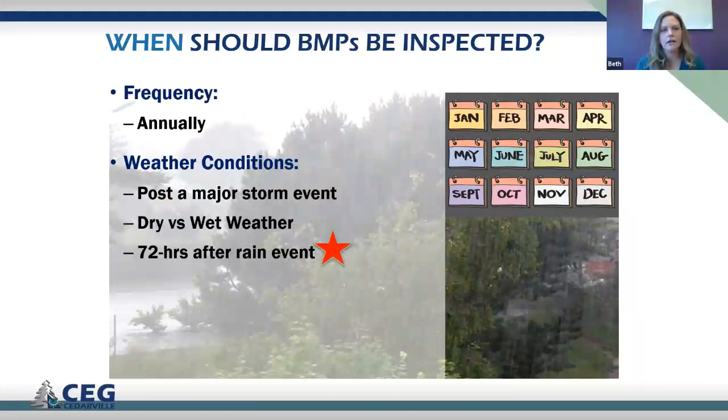And then when should the BMPs be inspected? In terms of frequency, if you're looking to answer the question on the annual report, it would be annually. Do they need to be inspected annually? That's really up for your municipality to decide what the necessity is. Maybe you conduct inspections 3 years in a row and there's absolutely no change to the condition of that BMP. You may decide that you can reduce the frequency of that. It's really your comfort level to be able to adequately answer the question and the requirements of the MS4 permit.